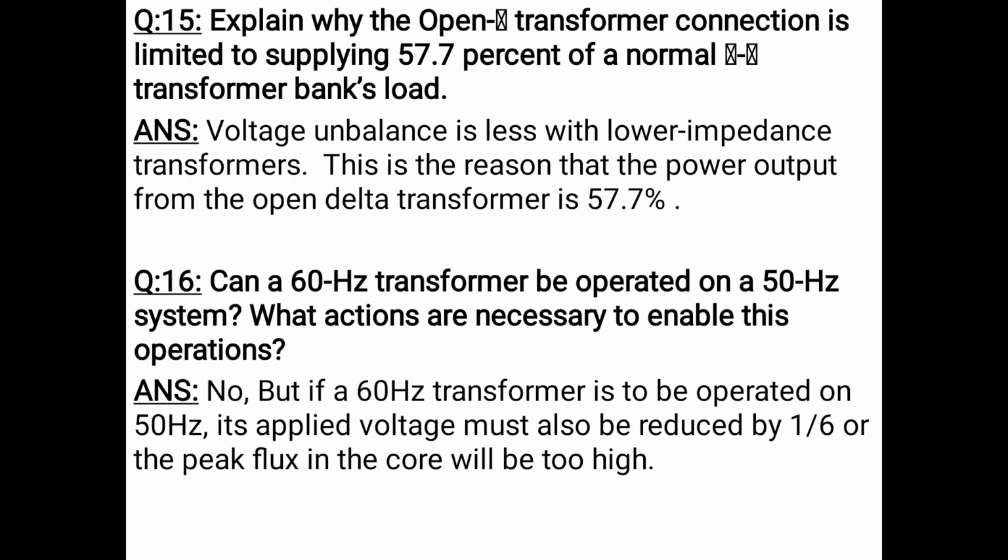Number 16. Can a 60 Hz transformer be operated on a 50 Hz system, and what actions are necessary to enable this operation? Answer: No, but if a 60 Hz transformer is operated on 50 Hz, its applied voltage must also be reduced by 1/6, or the peak flux in the core will be too high.